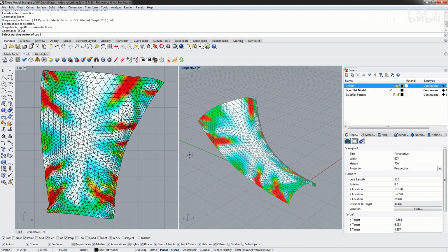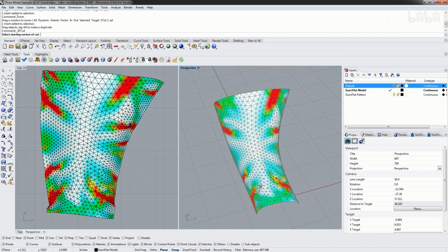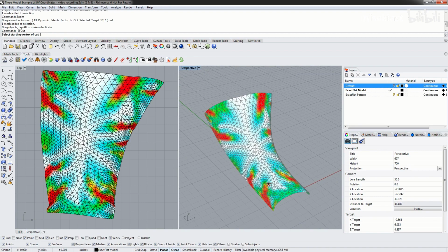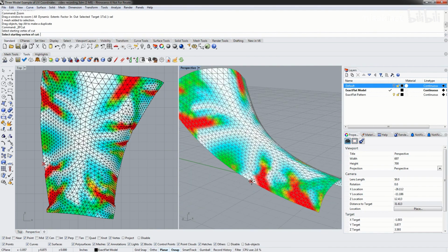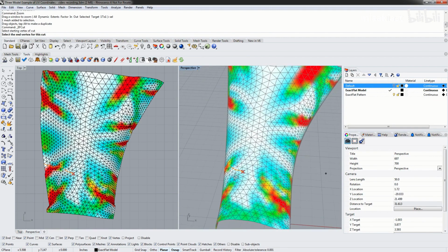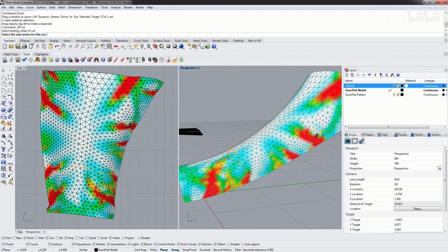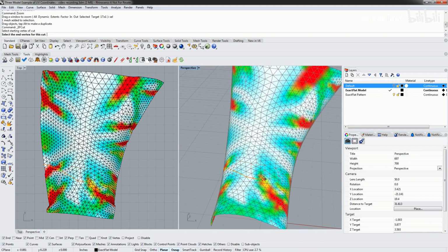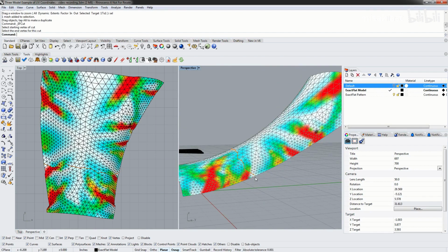the EF-cut command. The shortest path cutter works by allowing you to select a start and stop point for your cut, and Exact Flat will automatically determine the shortest path along existing triangle edges to form that cut. You don't have any control over where that path goes. However, instead of creating one cut from the start to the end, we can create multiple cuts across the path to create our cut profile.